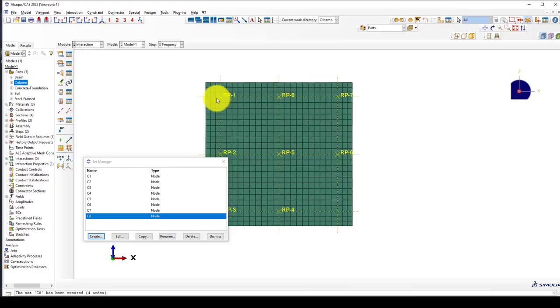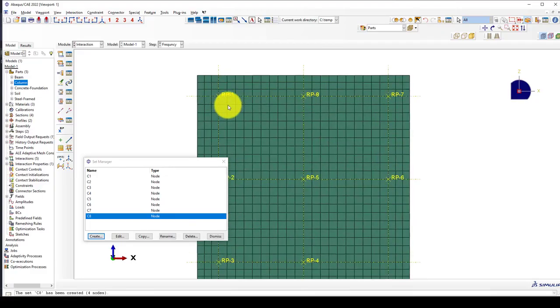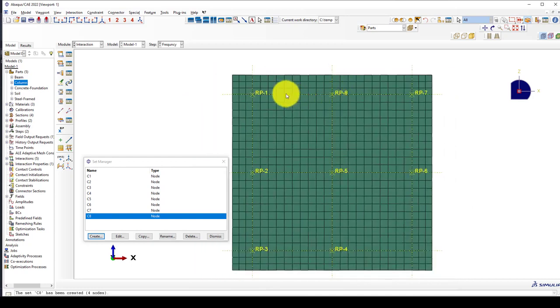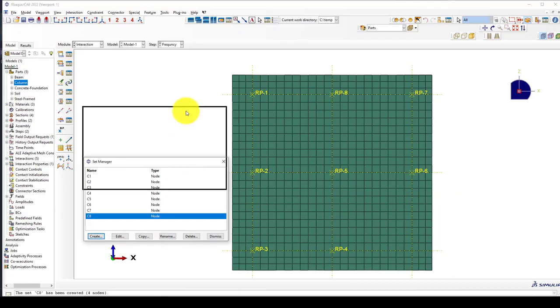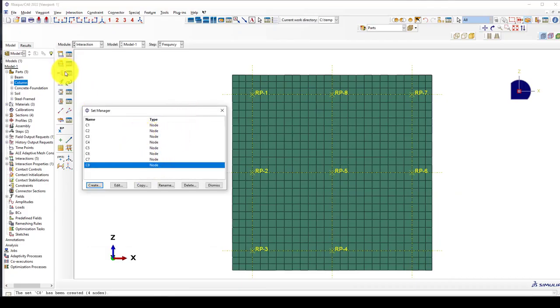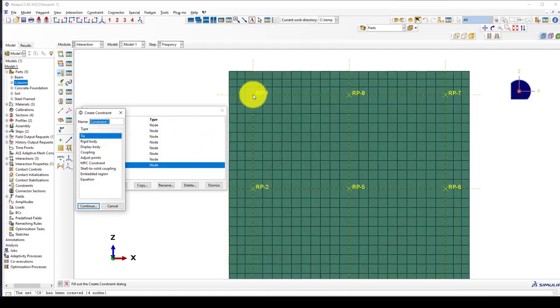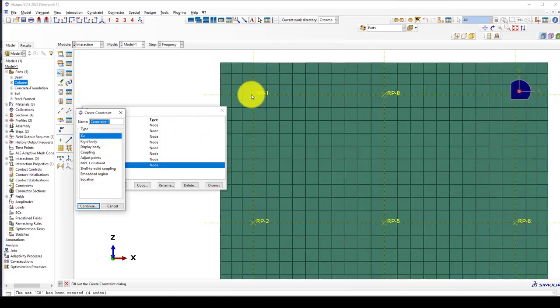So first of all, I want to consider a base plate with anchor is created in this region. Then the end of that point is the different point. So I want to then connect that different point to the end of the beam columns. So I can go to interaction, and I want a tie connection. So there is no movement. So exactly that tie.